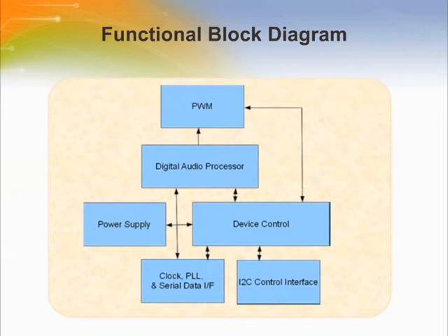The DAP arithmetic unit is used to implement all audio processing functions: soft volume, loudness compensation, bass and treble processing, dynamic range control, channel filtering, input and output mixing. The 8 channels of high-performance digital pulse width modulation drive switch output stages in both single-ended and H-bridge configurations.